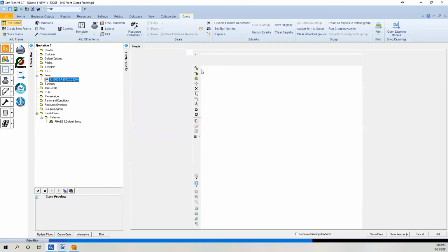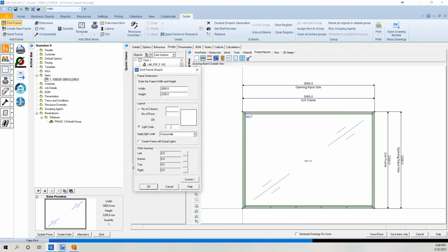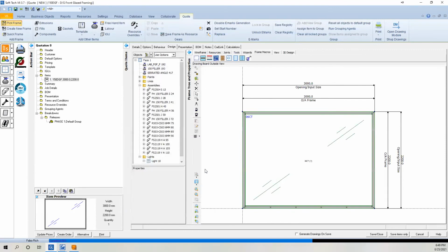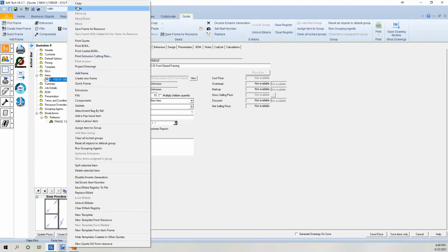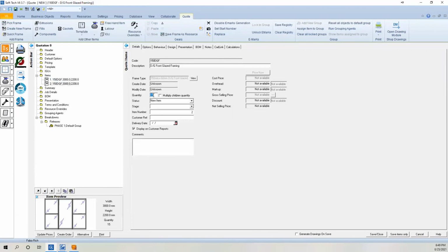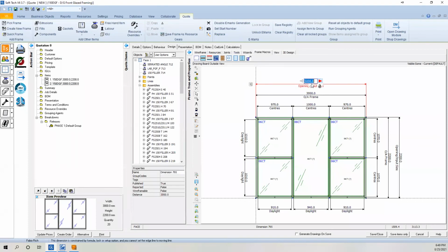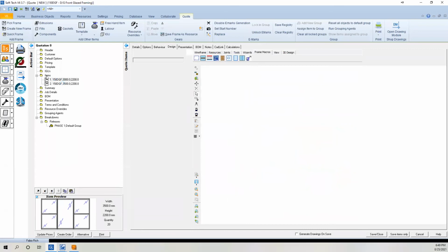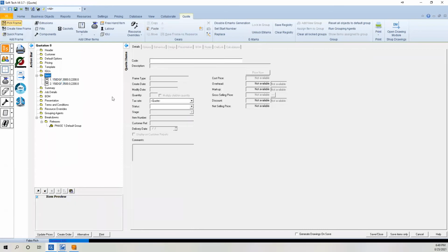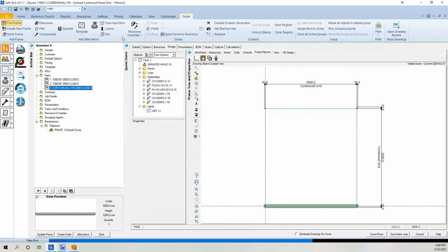So if I quickly add a few elevations, I will show you how you can use that functionality. So I go and say it's going to be 212. Let's say the quantity 15. Copy this, create one more. 20. Okay, change the size of it. So we have two different elevations, and then I'm gonna add a curtain wall with that same type of custom unit. Added.